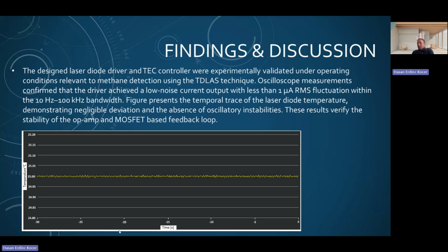Now we will look at the findings of this research. The designed laser diode driver and TEC controller were experimentally validated under operating conditions relevant to methane detection using the TDLAS technique, and we use an oscilloscope to measure the achieved low noise current output. This figure presents the temporal trace of the laser diode temperature, demonstrating negligible deviation and the absence of oscillatory instabilities.